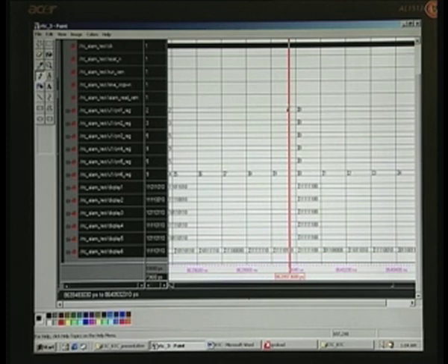So let us take this 235959 and then correlate this. Counter 1 must have a 1-to-1 correspondence with display 1. Let us say here A, B, C is 0, just keep track of this, then D, E, then F. C and F are 0, this should mean 2 because that is counter 1 value that must be reflected. I will just draw it for you here. So this is 2 here, and if you take this one, this is A segment, B here, then C is this one, C is 0, that is what we have here, then D here, E here, F here, F is also 0, so you can just see here F then G.